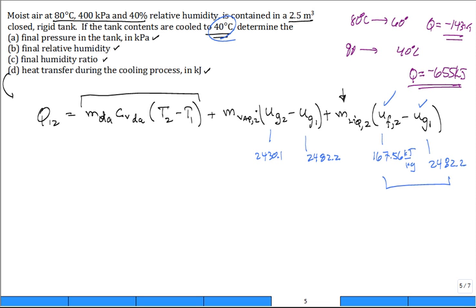So to do the energy balance correctly, we have to find out how much of that mass condenses. You could act as if none condensed, then you would calculate something like the relative humidity at the final state would be over 100%. So you'd have to backtrack. Here, just assume that it's saturated air at the 40 degrees C, okay?